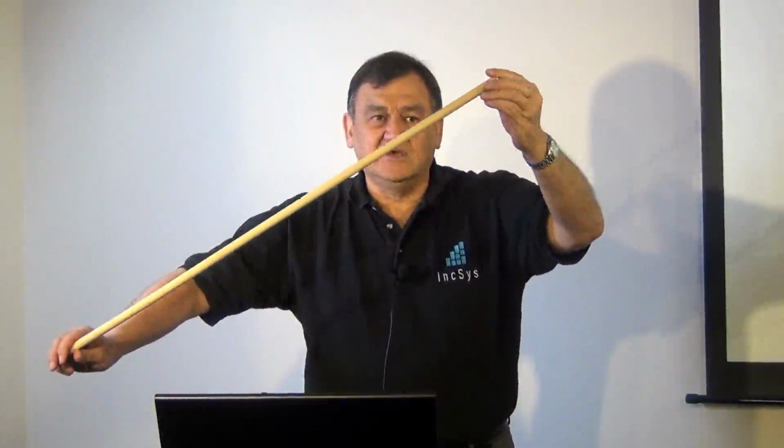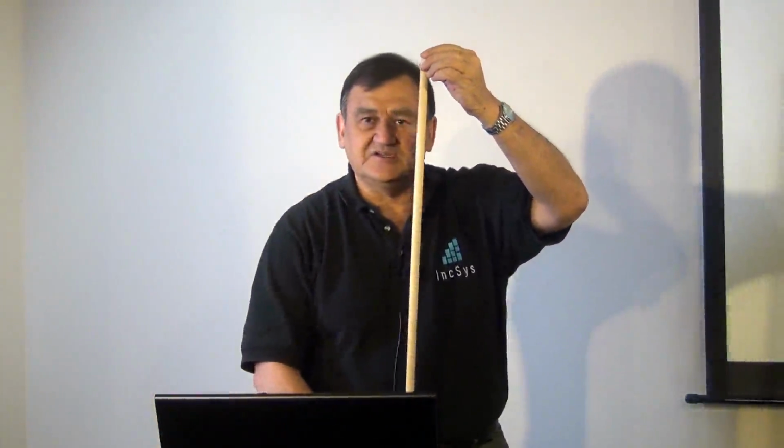You've got your power being absorbed by your inductors, and that can actually be complemented exactly by the power that is being generated instantly by your capacitors. And so that's why I draw the analogy between the potential energy, which can be the energy in your capacitors, and your kinetic energy, which can be the energy in your inductors. And those two forces are oscillating back and forth between each other at 120 times a second to have an exchange of energy in your system. But there's no net dissipation of power.